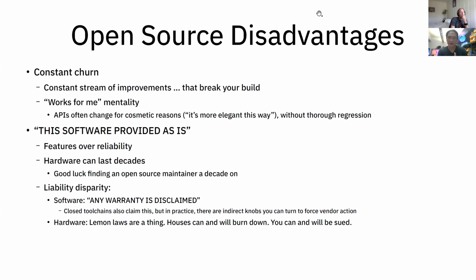So an actual example of the problem is that I shipped a product that has DDR3 memory on the inside of it, and you have to calibrate the DDR3 memory on a bit line basis based upon the SKUs and the yield of the device, right? And those calibration engines, when you actually ship hundreds of thousands of devices, you get to real corner cases. You're falling off the edges of the eye. You have loop arounds. You have a bunch of issues you have to deal with, and it takes a really long time to capture all those cases. The simulations aren't sufficient to capture those.